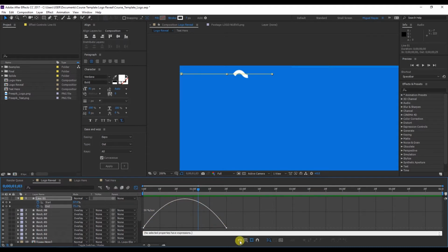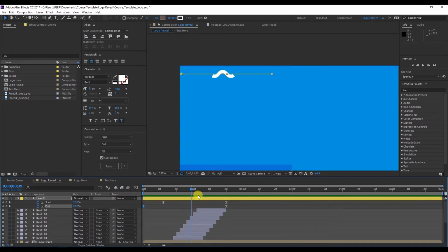So we'll go to the Speed editor and look for the anchor point, which will move here to the middle, pressing Ctrl to get a straight line. Do the same with the next one and preview. Now you see it's a lot faster, so we move the points a bit more and preview again. Okay, I think we have what we are looking for, the animation of the curved line.